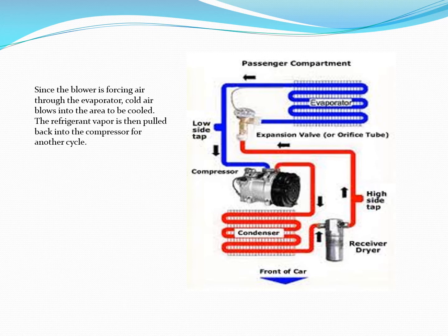Now, these systems here show you that this is an expansion valve system. I mentioned earlier that the expansion valve systems use a receiver dryer. You can see that located here on the high side. It's important to note at this point that if you have the accumulator dryer system, that means you have a fixed orifice tube for your pressure drop. So at this time, think about replacing the expansion valve with a fixed orifice tube.